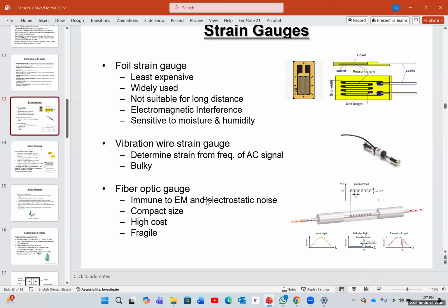Let's say it's 90 megahertz. Okay, so this inside is 90 megahertz and it's fixed. We don't change it. The only thing that we change is its amplitude. We're alternating its amplitude. The signal that we have on top, which is its envelope, is the information signal, and this is the carrier signal. This is around 30 hertz.